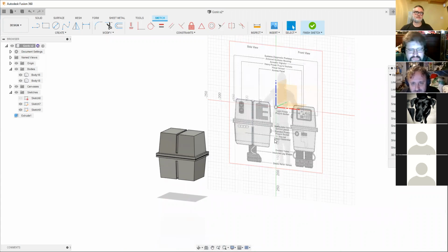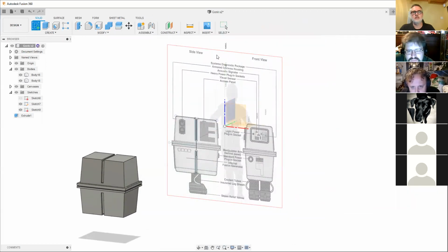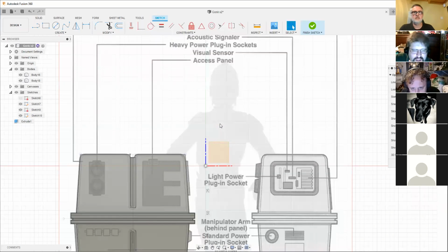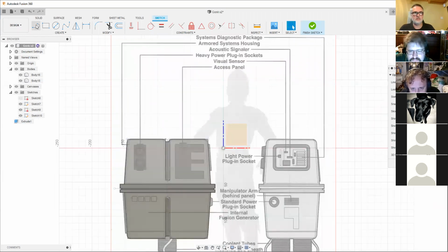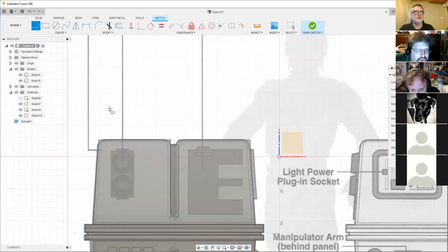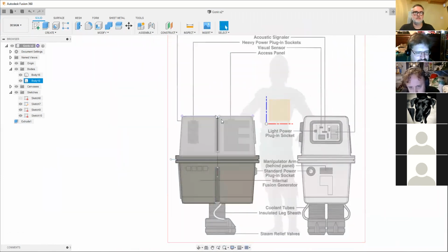Okay, I still have the sketch palette up. So how do you select the planar face? Mine's highlighting, but do you have the little eye next to origin? Yes, I can see the origin. So all you do is click on create sketch, and then hover your mouse over those three orange squares. Select the one that you want. The face that you want is this face here. And then it should put you straight on looking at that face, and then you can just go into the line tool. Wonderful. Now I have it. And then it's wanting to go square. Okay, good.